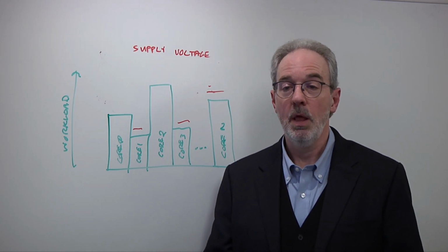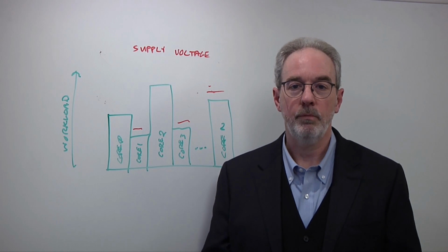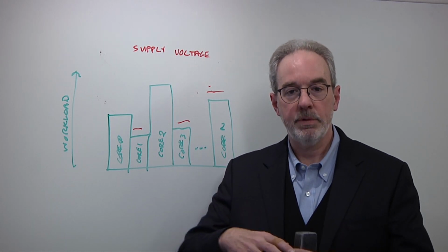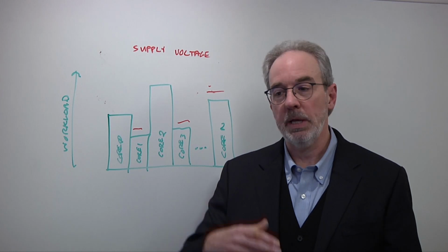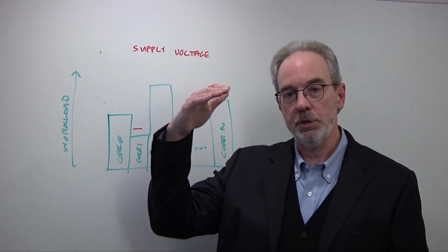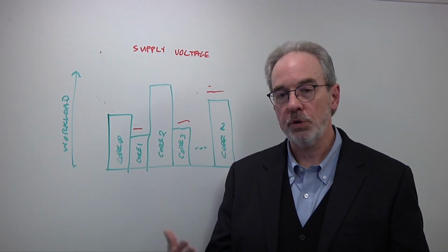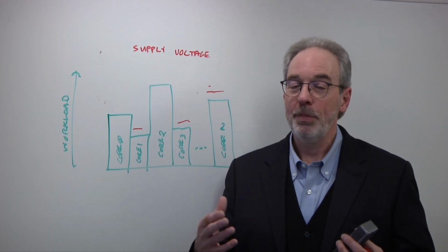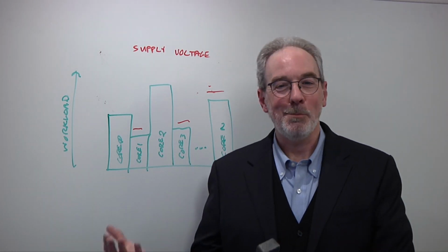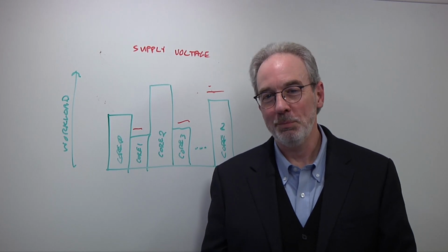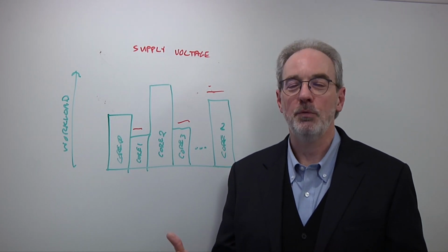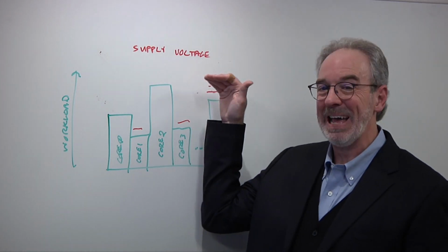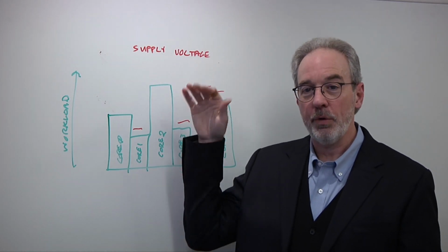The first is they will over provision their voltage because they don't want to have a design that's capable of failing. In other words, they will over margin to make sure that if there were any droops or any excursions in their power grid, it'll never get to the point where they'll experience a failure. That's fine, but again, going back to the customers and the marketing folks who are always pushing the parameters, giving up that much performance used to be an option. It's just not anymore.